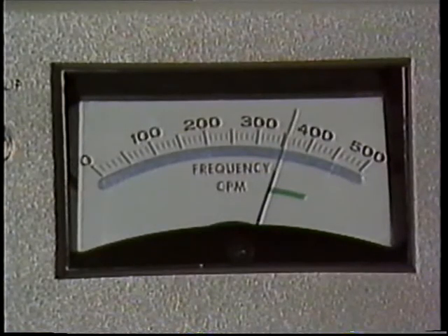This is exactly like an unbalanced tire. Each time an unbalanced tire rotates, the heavy spot vibrates when it makes contact with the road. As an unbalanced shaft rotates, the vibration produced by the heavy side is picked up as it passes the probe, 1 time every revolution. However, unbalance is not the only problem which can cause vibration at a frequency equal to 1 times RPM, as we'll see in a few moments.